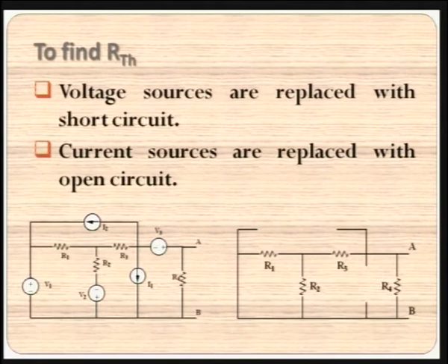This could be done using an ohm meter practically when we want to have the value, or it could be calculated using the typical equations we use for resistance in series, resistance in parallel, series parallel, using some symmetry technique. So, we are well equipped to find the equivalent resistor, because this has been discussed in the initial lectures. So, now we have got an idea of how to find the Thevenin equivalent voltage and Thevenin equivalent resistance. Thevenin equivalent resistance I have just now explained.